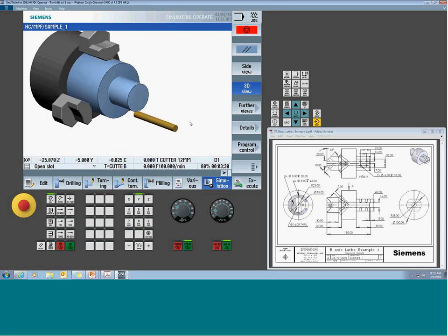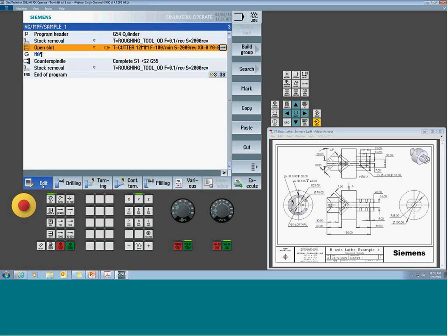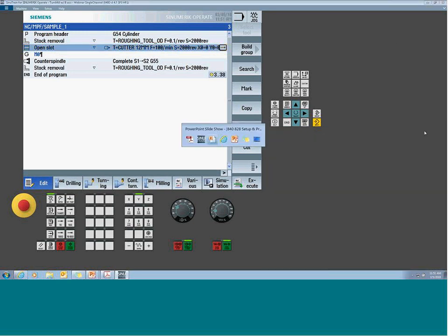With a face-wise strategy, you're not going to see the slot oriented to the C axis. If I use the face C, then the axis would be held stationary. And we get our slot. And the B0 position knows based on the location of the slot. And because I have my program stop, if I start again, it would have continued on, done the transfer, and moved on through the program.